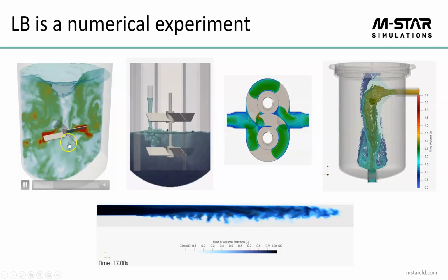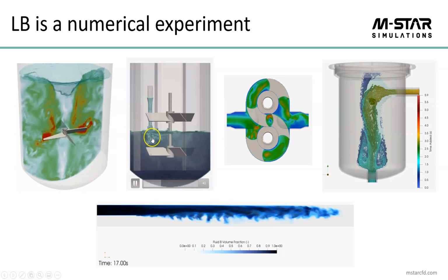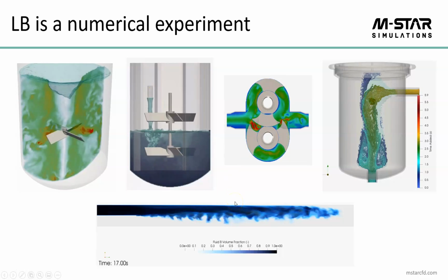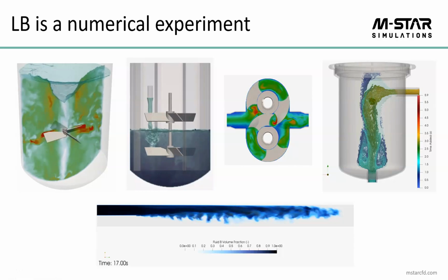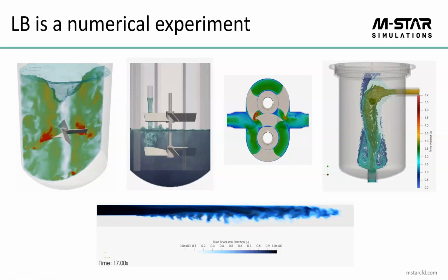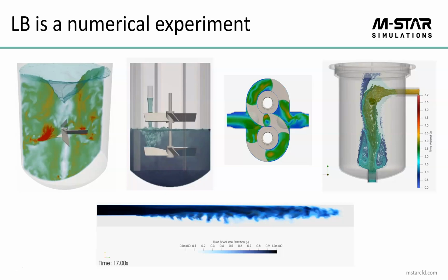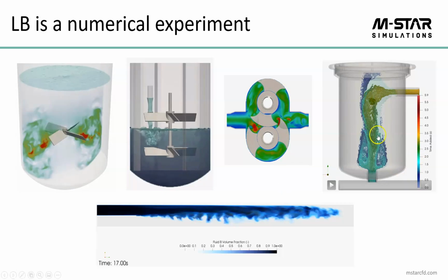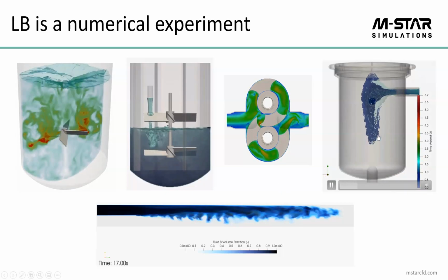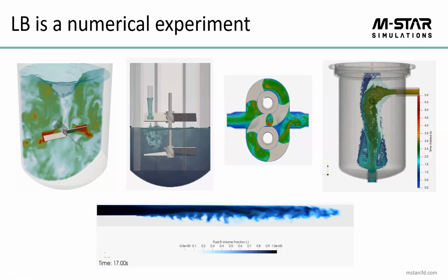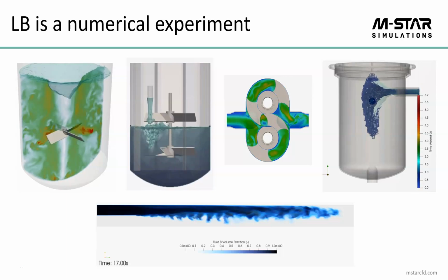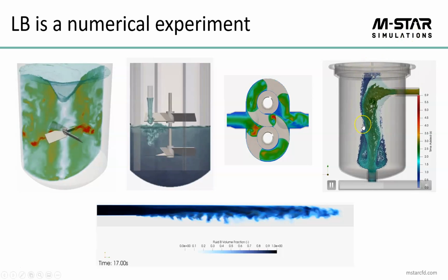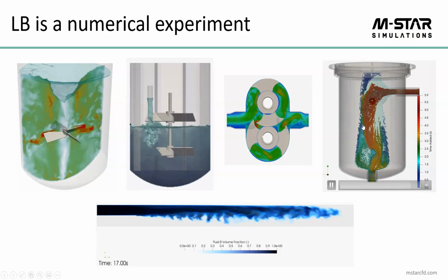And it's not just closed systems or semi-batch systems, it's open systems as well. Here is a Waukesha pump, pumping fluid, as it were. We can use this to understand the strains and stresses realized in a cell as it moves through the line. Here's looking at some surge tank here. We're examining the residence time distribution and figuring out whether or not we're going to get bypassing, and spoiler alert, we did. We got a lot of bypassing here within the context of this vessel.